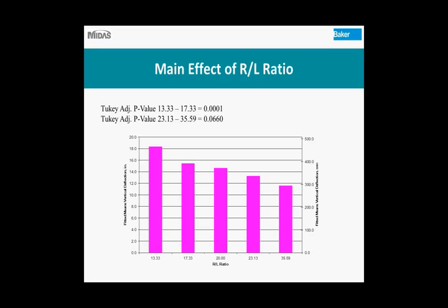Those are for the bridges that have the 300-foot radius. And then for the 13.33, that's our largest unbraced length at 22.5. And when we move to 17.33, our unbraced length is smaller at 17.3. So this graph shows moving our cross frames closer is going to reduce the deflections that we're seeing during construction.